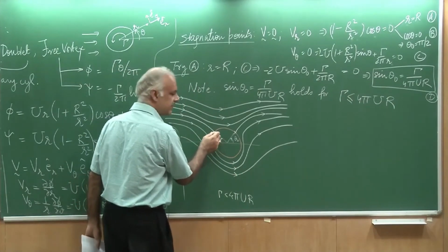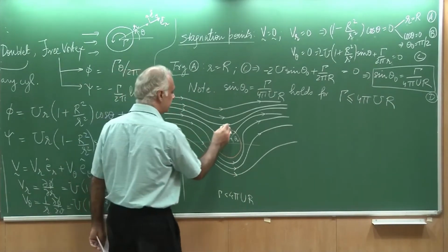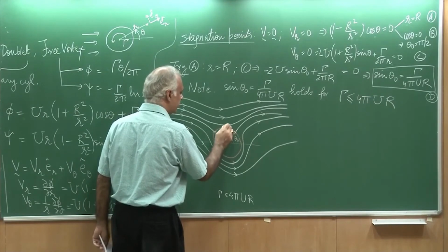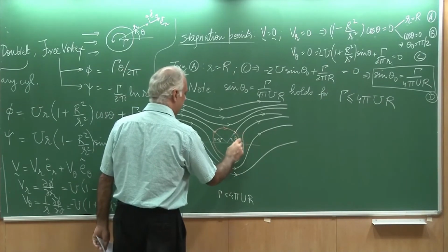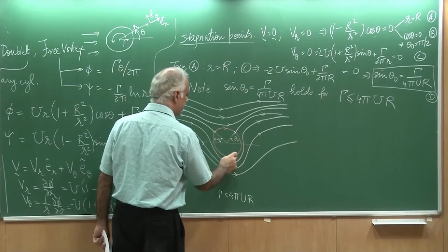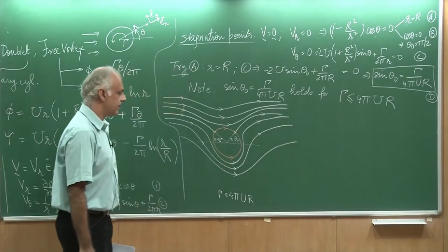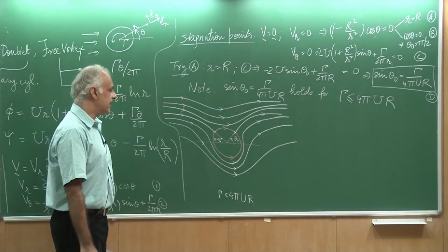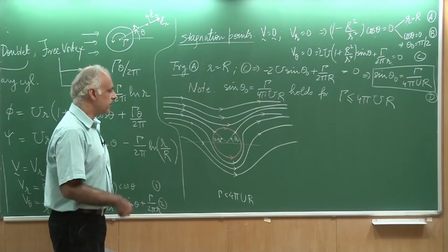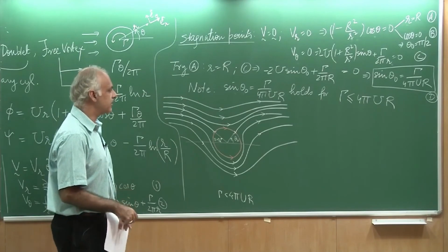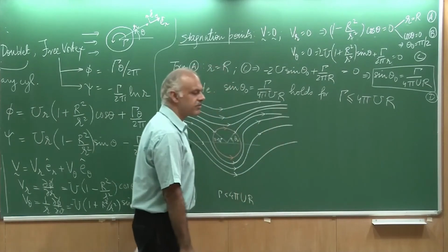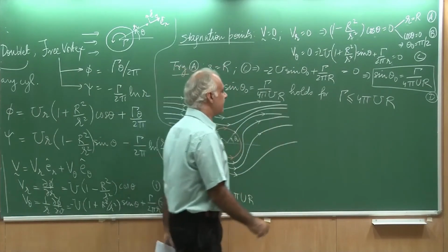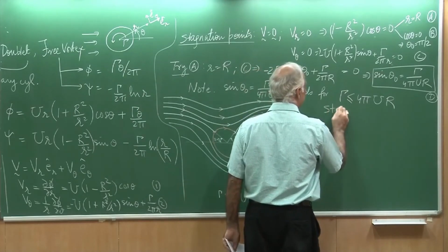This streamline is very interesting, on the surface of the cylinder. Between the two stagnation points, on the upper surface they go in the clockwise direction, and the ones on the lower surface actually go in a counterclockwise direction. And I am not going to draw the streamlines inside the surface of the cylinder. So you must be wondering how I drew these streamlines. Well, the formal step would be that after identifying the stagnation points, I first get the equation for the stagnation streamline.